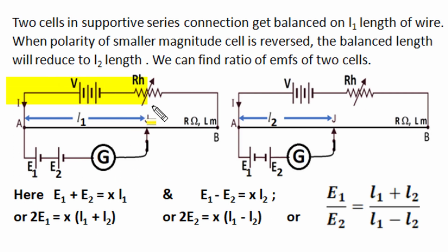As usual, the primary circuit is connected to a source voltage with a current limiting rheostat, and a certain amount of current and potential gradient is established in the AB wire. Now the two voltages which we have to compare are put in additive series combination, such that the high potential terminal of this combination gets connected to the high potential terminal of the AB wire, that is A, and a corresponding balance length is obtained on the AB wire by suitable positioning of the jockey contact.